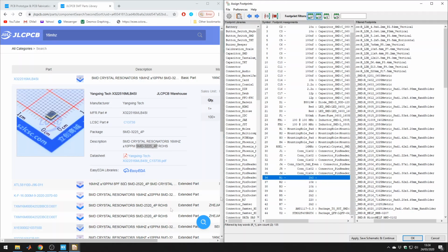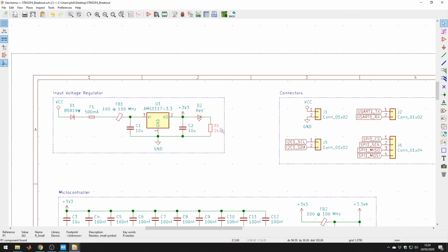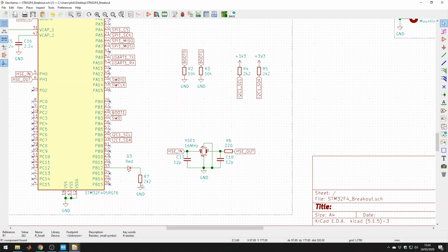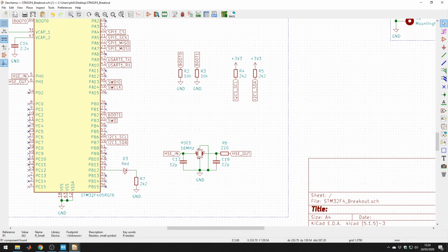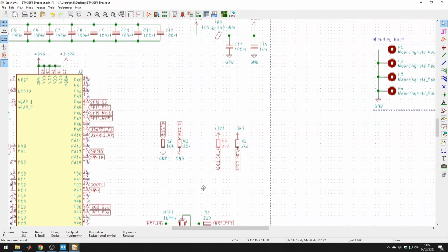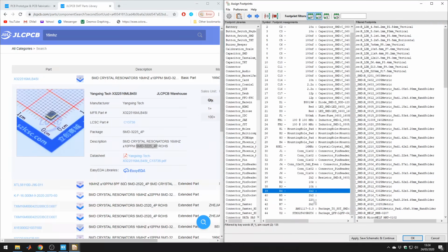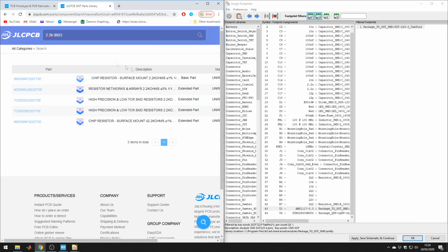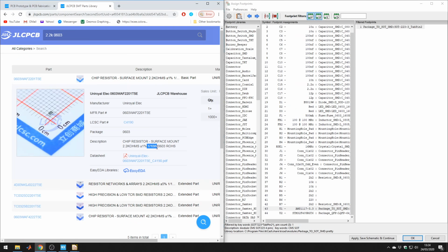For LED resistors, for example, the ones we have here, R1, which is 2.2K, and R7, because of the large value of resistance and the low voltage, there's not going to be much power dissipated in them. But for good practice, I choose a larger resistor for LEDs. So I'll choose 0603 for the 2.2Ks. That was R1 and R7. Now, always a good idea to check 2.2K if they have them in stock, which they do. And it's a 1/10 of a watt, which is fine, plus minus 1% resistors, 0603, perfect.